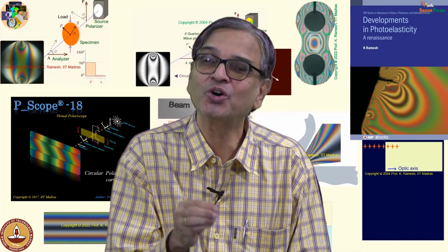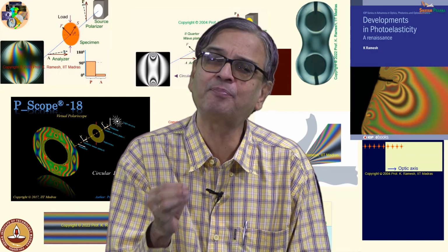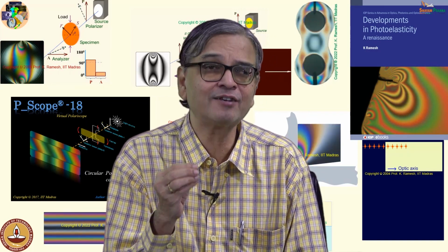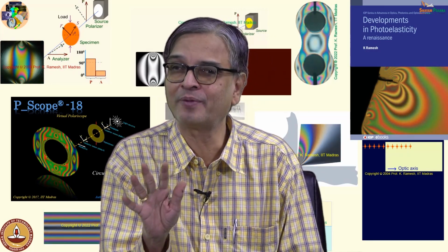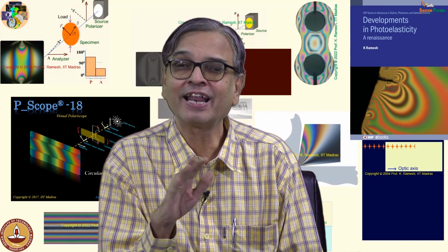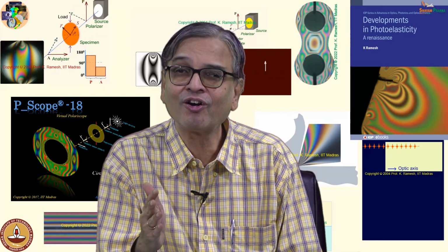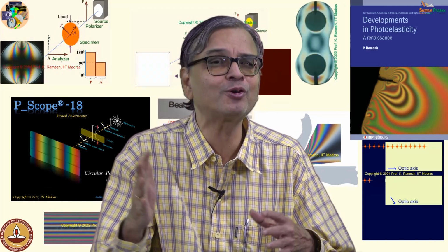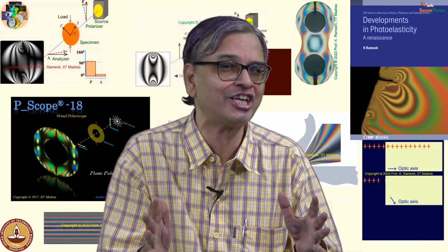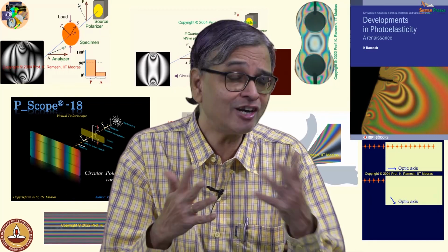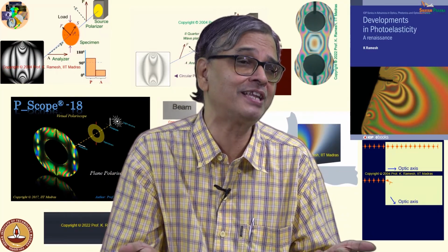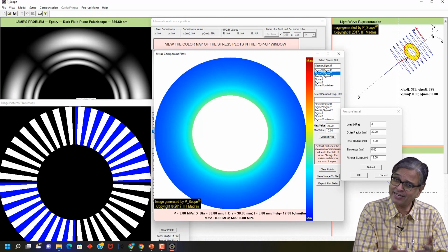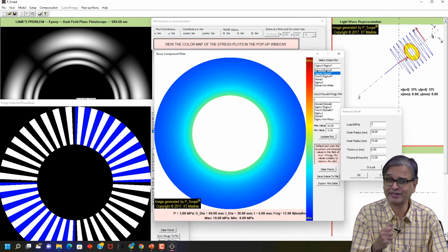Okay. So, you also understand a very subtle point. The greatest advantage of living in linear domain, that when I double the load or half the load or change the load in a linear proportion, in the same proportion stress magnitudes change, principal stress direction cannot change because I have the ratio remain same. That you can get a grasp of it.